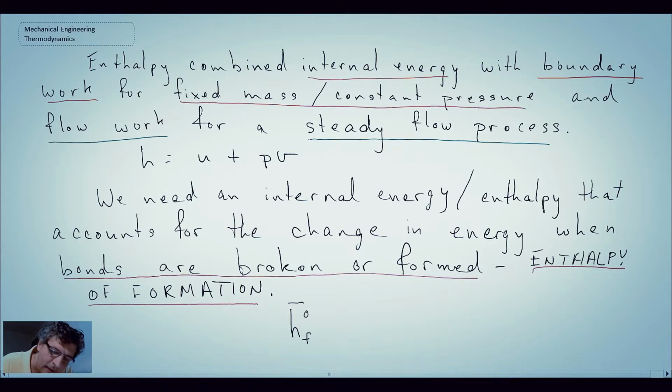So the different things that we have, the overbar, that's because it's on a per kilomole basis, which we will find to be quite convenient when we're dealing with stoichiometry and chemical reactions and the balance, the number of kilomoles either on the reactant or the product side. The 0 references a standard reference state. So that means that this property has been determined at a standard reference state.